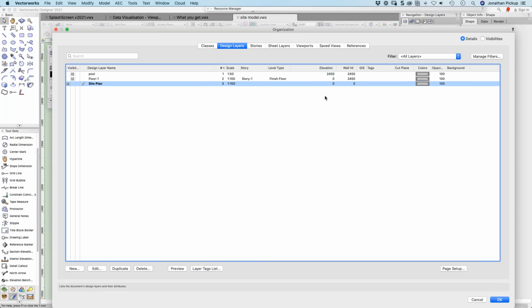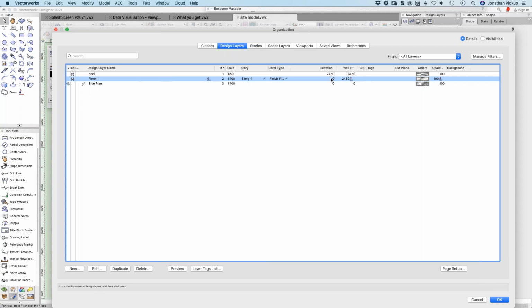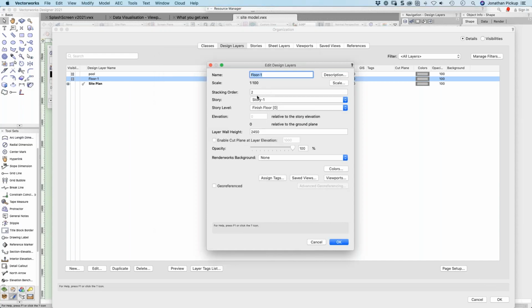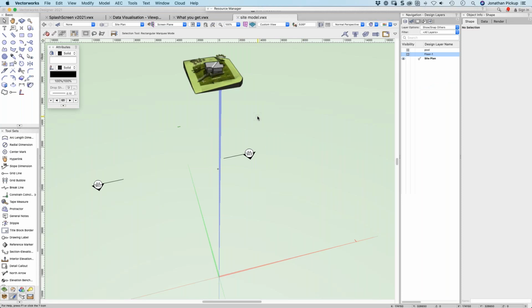You probably remember, Jane, what I do is I set the elevation of the site plan at 0, and then my floor will be the three-dimensional height that the survey has given me. So if, for example, the floor is at 40 meters above sea level, then the elevation here would be 40. Hmm. Yeah. Well, I'll figure it out. I've had it working before, but not on this project. Oh, that's where the problem is. There's something else to look out for.